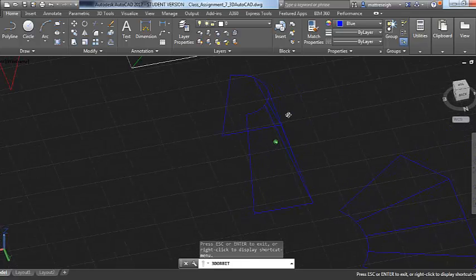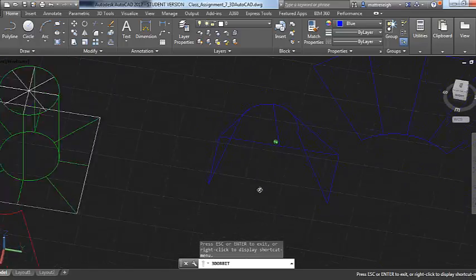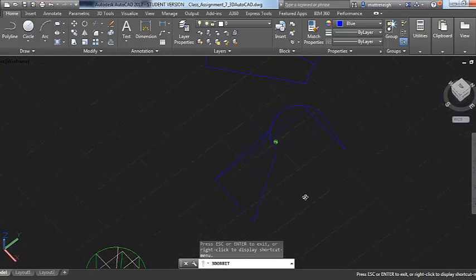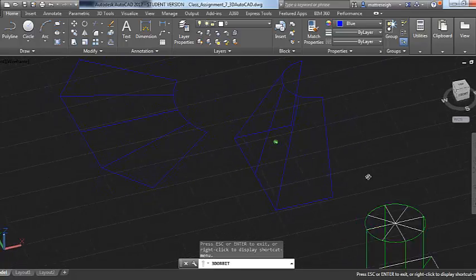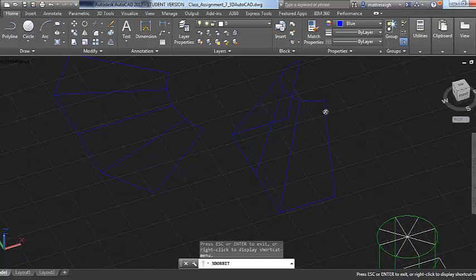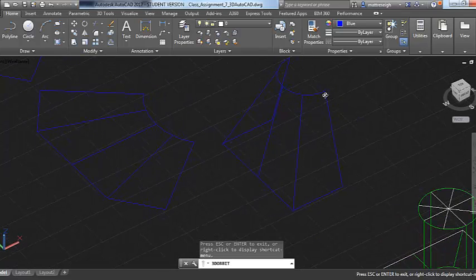Yeah, and I've got to get my 2 corners to spin 90 degrees, which can also be hard to hold in the press brake, especially if the part is heavy. It can be hard to hold all that in the press brake and get all that to come around, because if I look at this now, I'm going to be press braking from this corner down to this corner in a various number of hits.